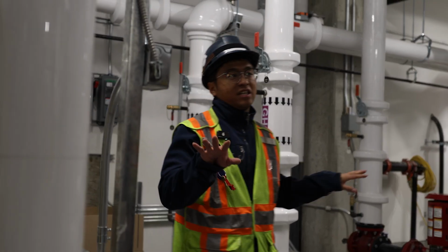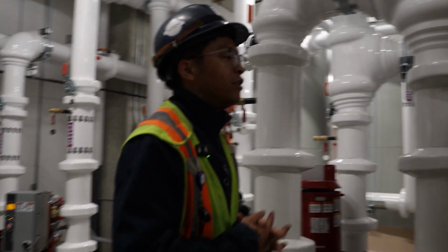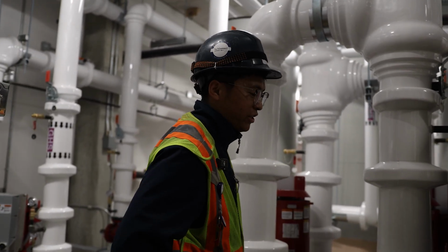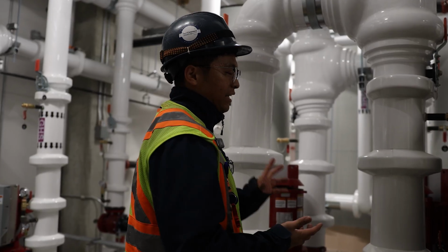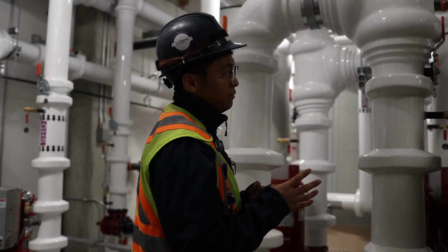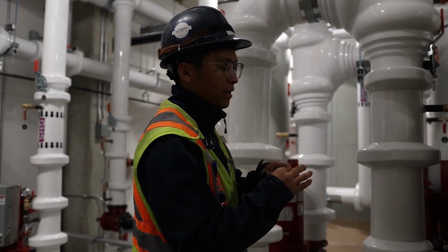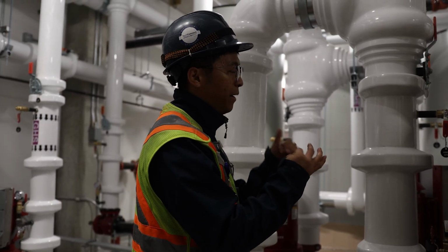This pump is a fixed speed. It's a constant speed. So there is no need for the differential pressure because it's not maintaining the differential pressure. And we can see the pump status. We can see the pump feedback. What is pump feedback? What percentage of the speed the pump is running?